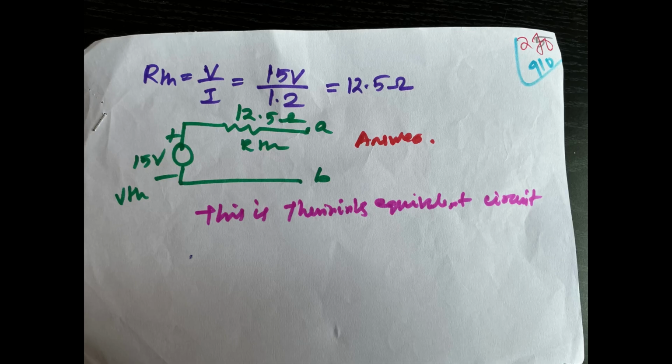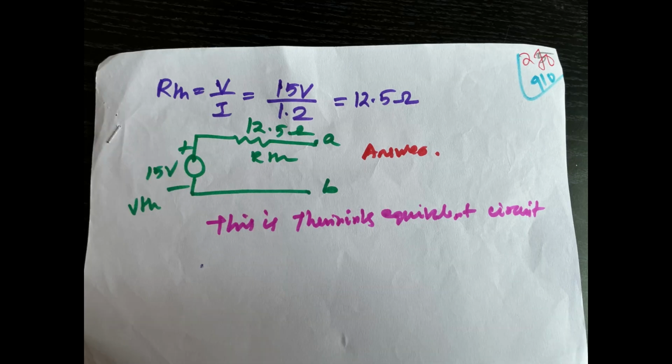Again, I explain the procedure. Consider the circuit with nodes A, B, C, D. B is the reference point. The reference point voltage is 0 volt. Apply the nodal analysis method: node A forms one equation and supernode DC forms two equations. From these equations, we find the VA and VAB value, this is the Thevenin voltage. Then form the short circuit. From the short circuit, we find the short circuit current value.